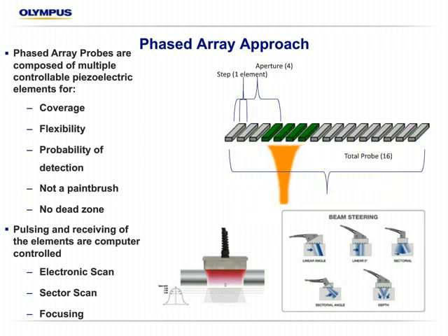And typically this is the normal approach for detecting corrosion, 0 degree, as it always has been, even when we go to phased array. But phased array does offer the benefit of the flexibility of steering the beam, so we could actually change that to 45, 60, 70 degrees, depending on what we're looking for, and we could have it rastering at that angle at the same time, depending on which probe we're using. Or we could do a multi-angle sweep of beams in order to detect off-axis defects, some of those unique damage mechanisms like stress corrosion cracking and H2S that might be oriented at different places, or any other given angle.